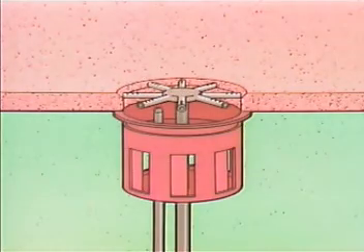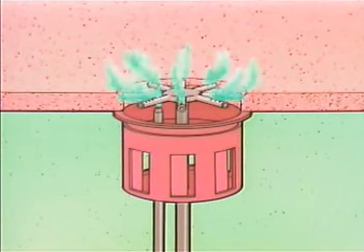All of the parts and systems associated with a furnace are used to accomplish one basic task: heating a process fluid. We can get a better understanding of how this is done if we break the furnace operation down into three basic actions. In the first action, air and fuel are introduced into the furnace and then mixed together by the burners. The mixture is ignited at the burners. As the fuel burns, a chemical reaction occurs and heat is produced.